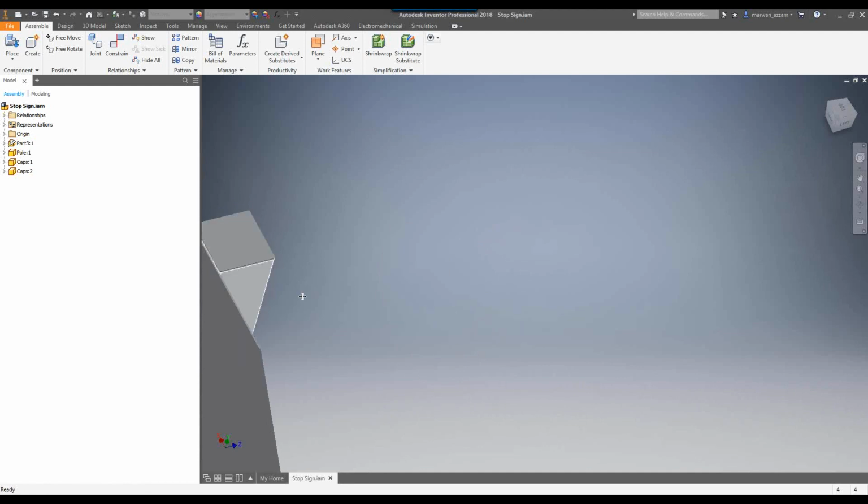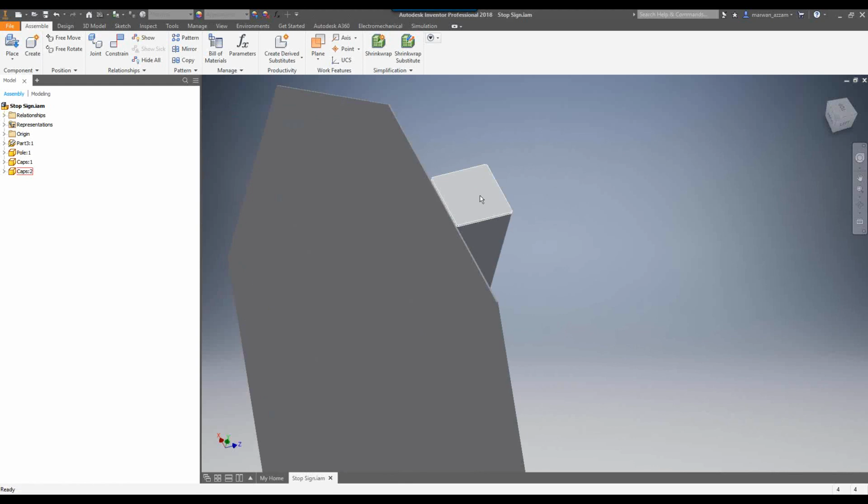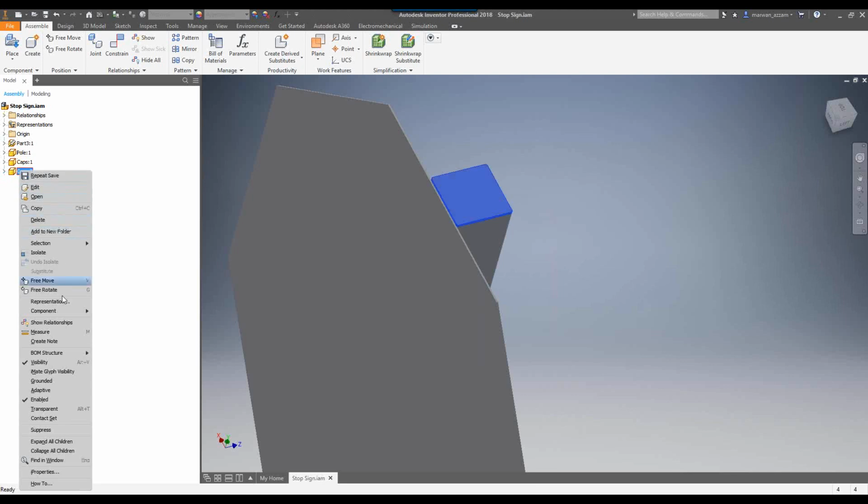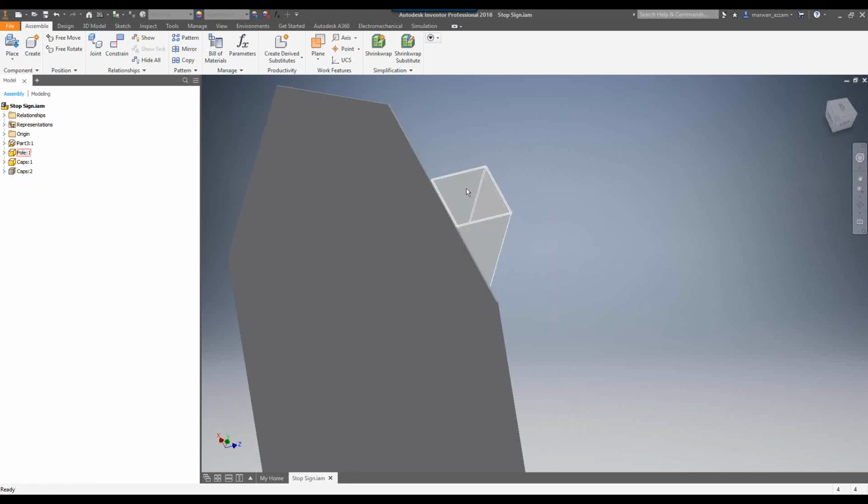Well, actually, it will generate the internal fluid, but this way it's not connected to the external fluid. When you import this into CFD, it will fill because this is not a solid pole. If I hide this, you'll see it's a hollow rectangle for this beam.